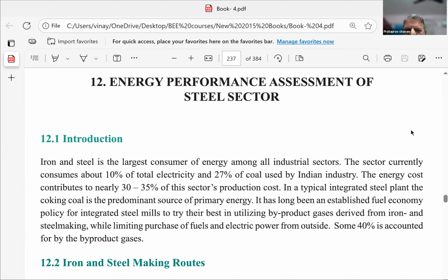What is the heat content in, say, for example, flue gas? What parameters should you know? Total heat transferred by the gas or extracted from the waste gas is how much? Our universal formula, mCp delta T. Right? Now you are familiar with this formula. M is the mass, either in kgs per hour, kgs per day, whatever.